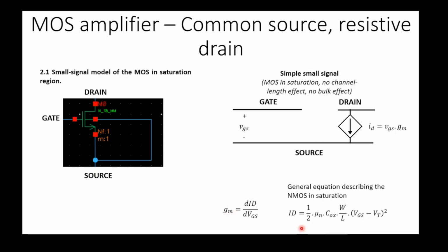This definition is only to give the intuition or understanding about the transconductance, but in simulation we don't need to care about it. When we already put the appropriate width and the appropriate value for the resistor, it means we put our MOS in the appropriate saturation region, or the DC operating point.